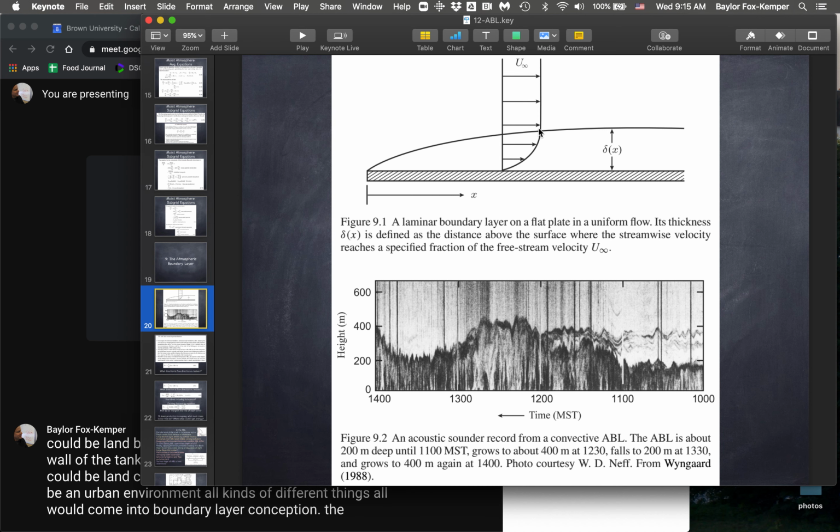The main dynamics of a boundary layer are that there's a finite width to a boundary layer because the conditions that govern the free flow away from the surface are different from the conditions that arise when the frictional or turbulent terms become important in order to satisfy the boundary condition here at the bottom. So if we scale the equations and find some depth scale for the boundary layer, that would be the scale over which those extra terms might be more important.